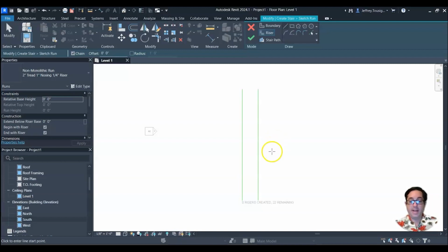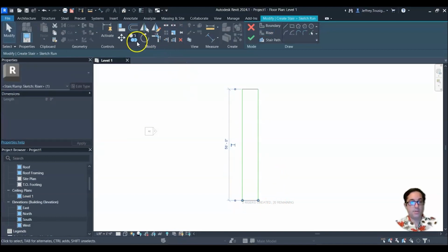So this is where you're going to have to get into your basics of calculating stairs, which you may have covered in codes or an early studio class. But we're going to need to draw in our risers based on distances that we would need to calculate. But just getting into developing the form of these stairs, we have our left and our right boundary line. We're always going to have an end riser line, and we're always going to have a start riser line. And then you just need to go from there and figure out how else your lines are going to be calculated out.